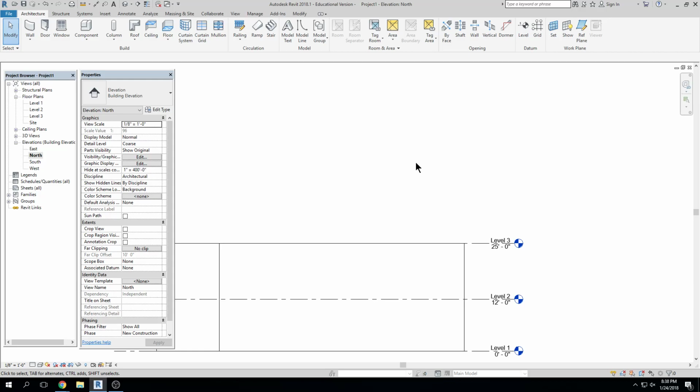So right now you're like, well, big deal, we'll just draw it without those things and who cares? But we're establishing elements that have relationships to other elements, and we're going to have to put a ceiling in. Speaking very generally, the ceiling will attach to the bottom of the joists of that main level. Then you'll have your joists, and then your other floor, and the ceiling of the second level will attach to the bottom of the joist of that second level. So you have to have these datums and these levels that mark all of these elements within this building to create other elements of the building: the floors, the stairs, the ceilings, the roof, all of these things, okay?